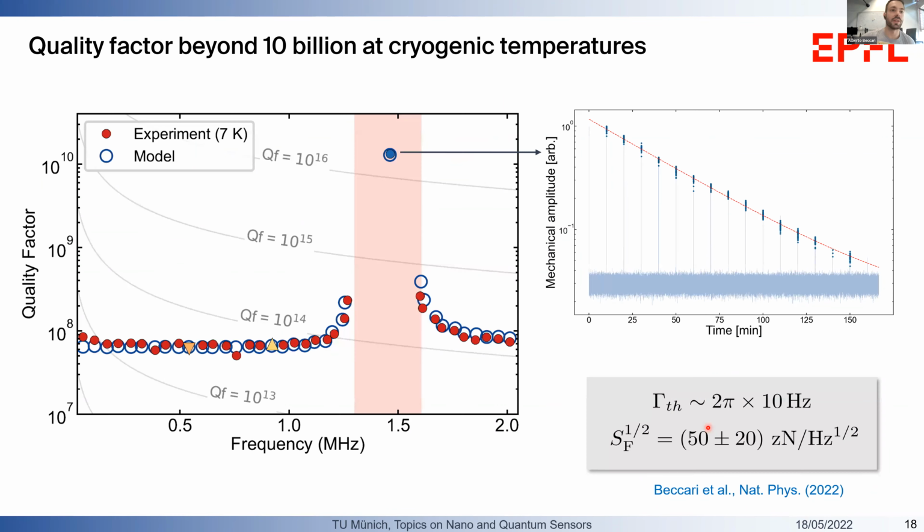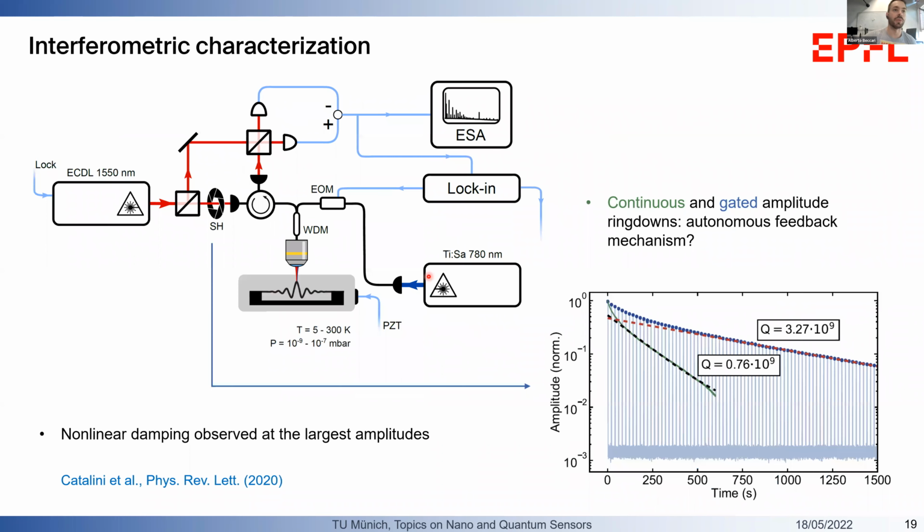So, just as a side remark, all these different quality factors for different resonances, we measure them in such an experimental setup. It's a 50-50 nanometer infrared interferometer that we built for nanomechanical displacement measurements. As far as I know, the only reliable way to measure damping rate and quality factor for very high Q mechanical oscillators is by doing a ring down measurement.